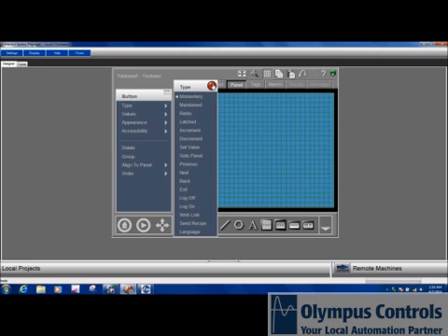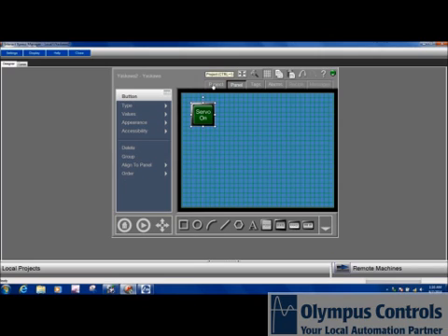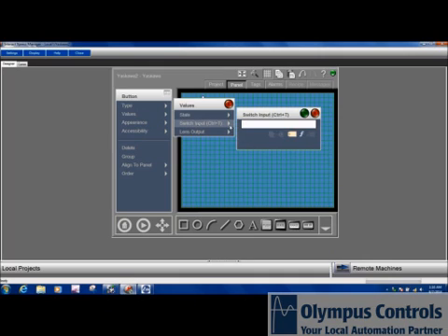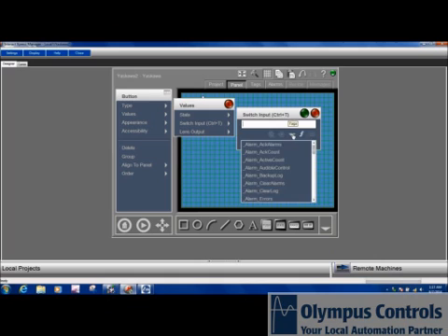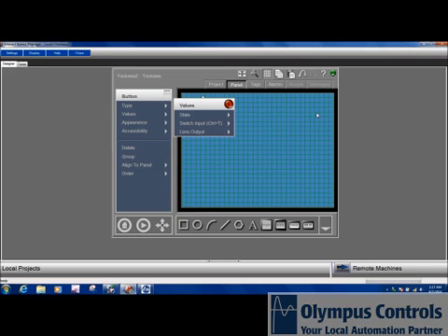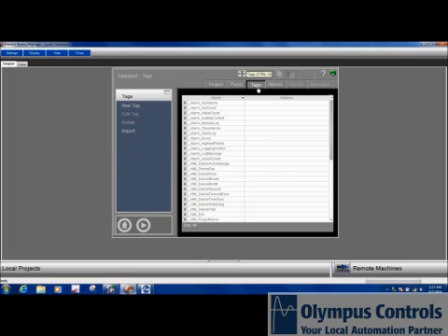The PLC ladder logic is written in such a way that it just needs a momentary toggle of that servo on bit for it to enable the servo drive. That servo on instruction works exactly like the Allen Bradley servo on instruction. Okay, so in order to do that, I need to connect this switch input to a tag. And if I look here, I don't have any tags from my PLC yet. These are internal system tags from InTouch Express. So I'm going to have to import in some tags first.